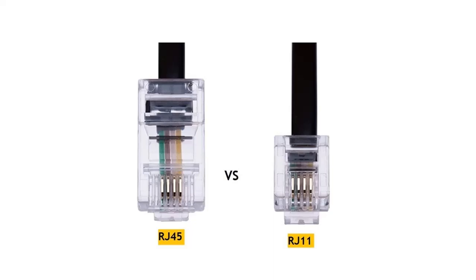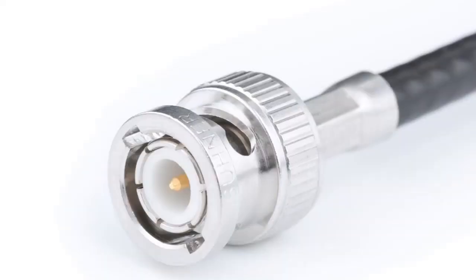The BNC connector is a type of RF connector that is used with a coaxial cable. BNC stands for Bayonet Neill-Concelman, and the BNC is used with both analog and digital video transmission as well as audio. Now these connectors are not very common anywhere, but they can still be found on older networks. There are many different kinds of BNC connectors.